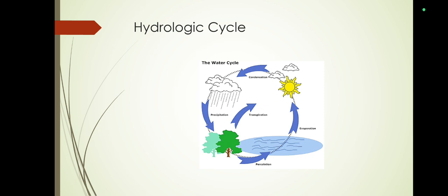A part of the precipitation may evaporate back to the atmosphere even while it is falling. Another part may be intercepted by vegetation, structures, and other surface modifications, for which it may either evaporate back to the atmosphere or move down to the ground surface. So, the portion of water that reaches the ground enters the earth's surface through infiltration, enhances the moisture content of the soil, and reaches the groundwater body.